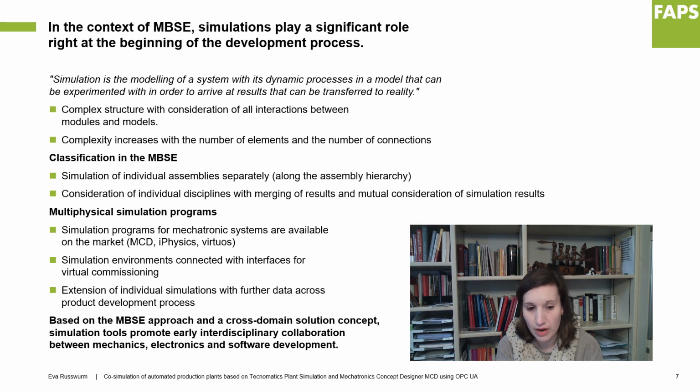Multi-physical simulation programs are already available from various manufacturers that are predestined for solving mechatronic requirements. Examples for this are the Mechatronics Concept Designer MCD, iPhysics from Machineering, or Virtuos from ESG. These systems not only offer a simulation environment, but also interfaces to use virtual commissioning. There are tools for mechanical and electromechanical simulation, manufacturing, tool and fixture design, quality inspection, and mechatronic concept development.